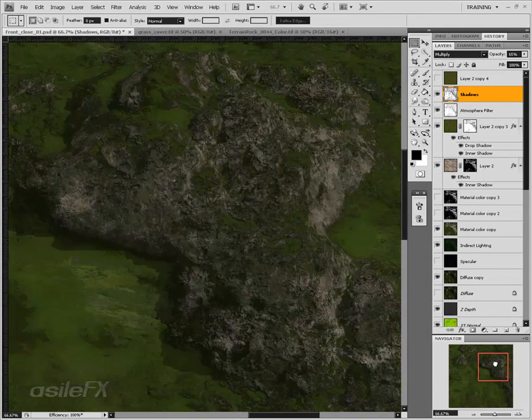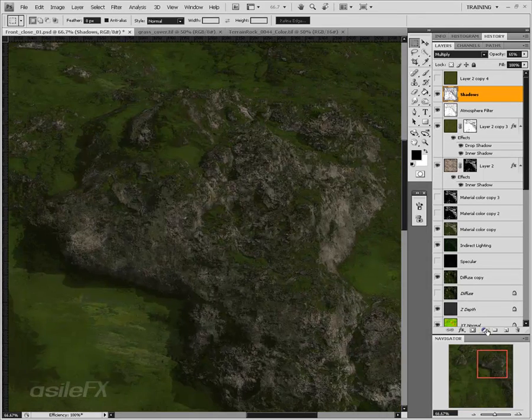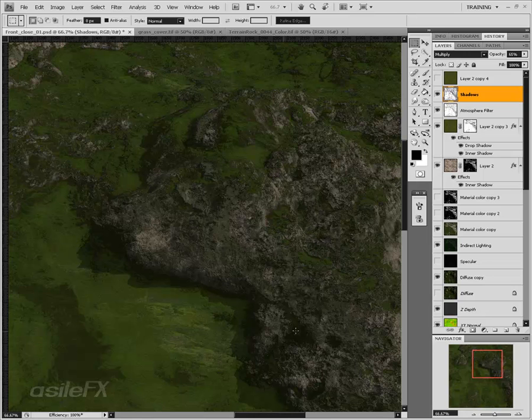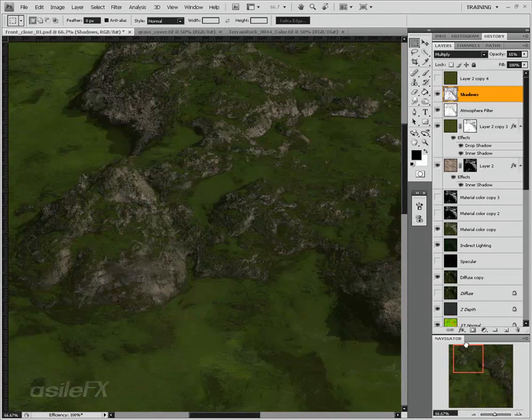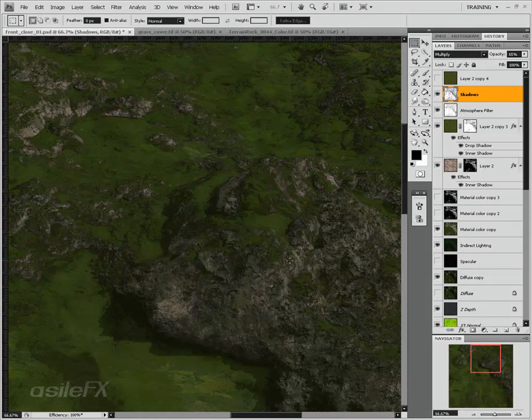So one really useful thing, and unfortunately I didn't do it for this image, was basically to take the material and turn off cast shadows before you render. You'll still get the diffusion, but you won't get the large shadows being cast onto the other parts of the terrain, but you'll still get the detail elements.